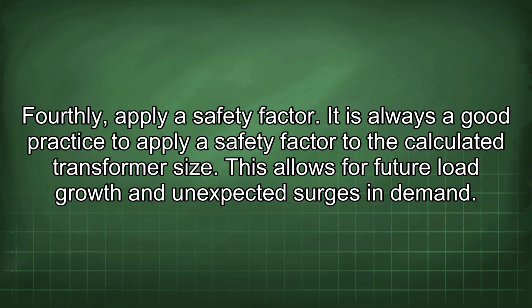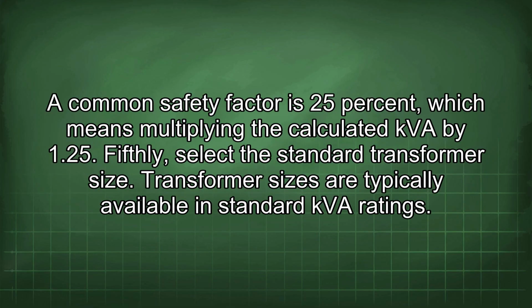Fourthly, apply a safety factor. It is always a good practice to apply a safety factor to the calculated transformer size. This allows for future load growth and unexpected surges in demand. A common safety factor is 25%, which means multiplying the calculated kVA by 1.25.